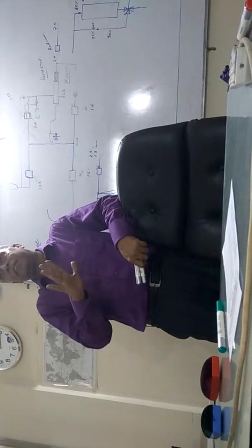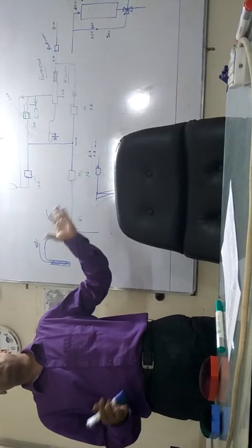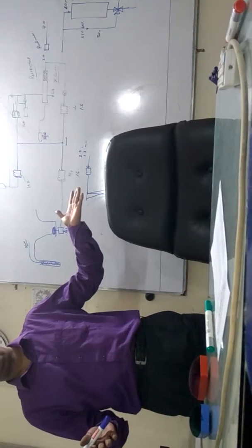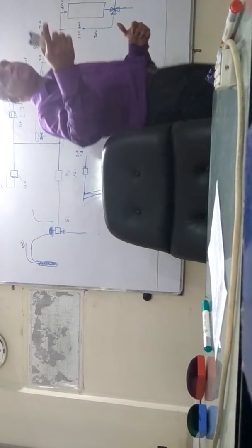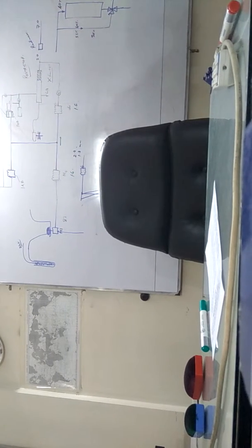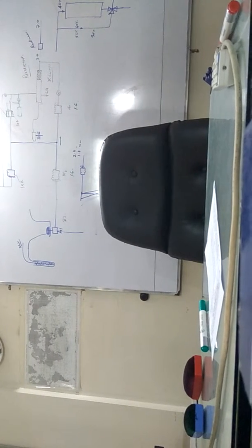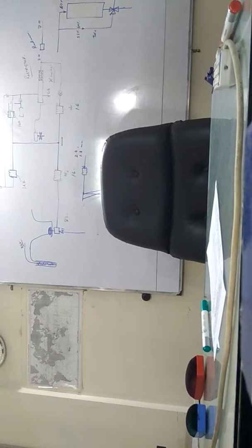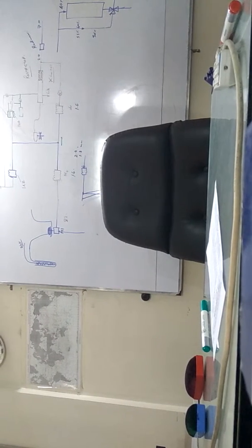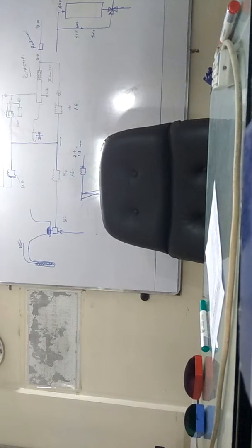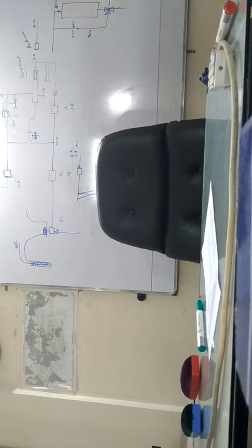But under these circumstances, this is good, because in this situation there will be no overshooting. Because if I walk, I can stop within 100 meters, but if I run, I could not stop there. Makes sense to you? Yes. So that is the function of the proportional action. It helps to overcome overshooting. Yes, and hunting. Agreed?